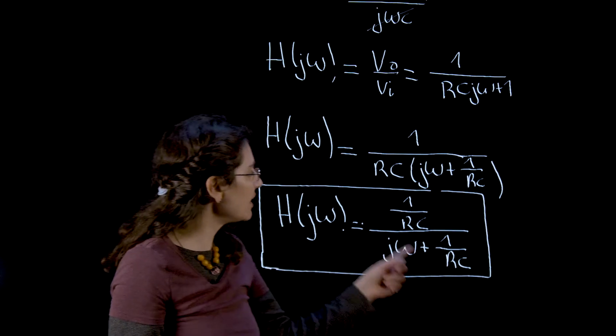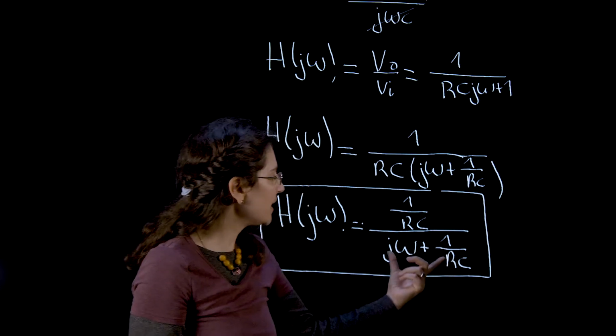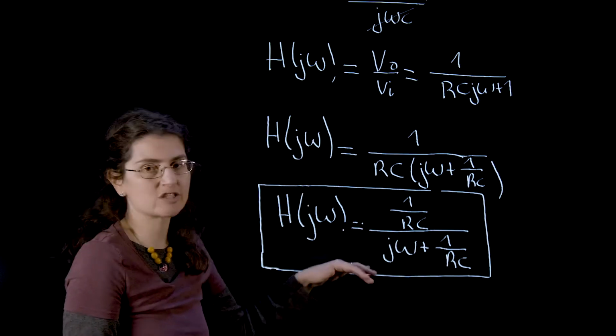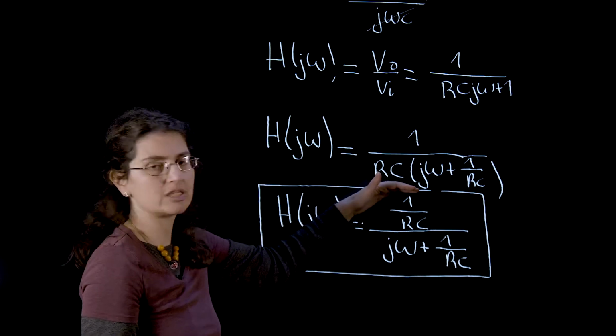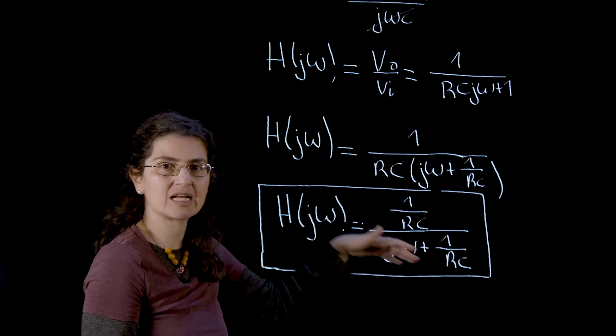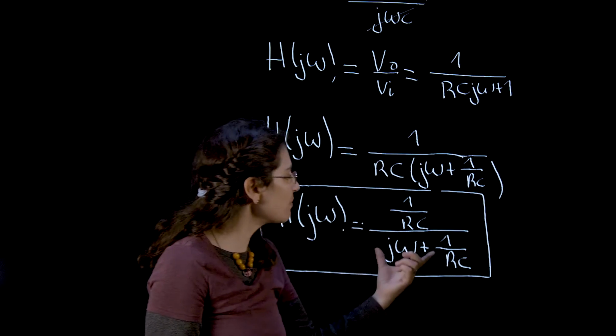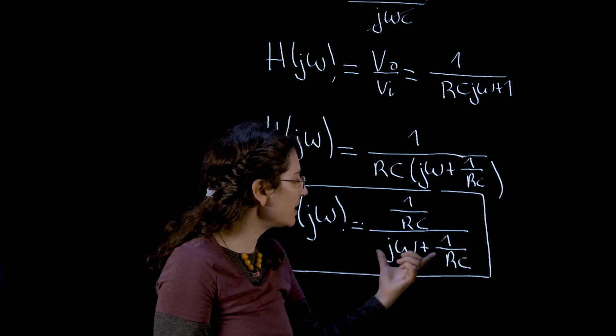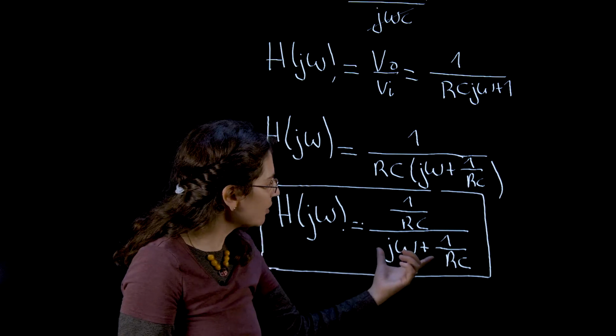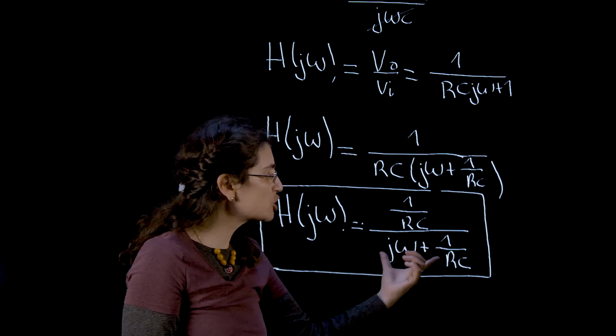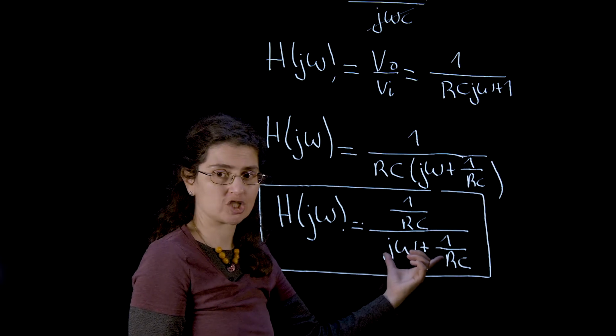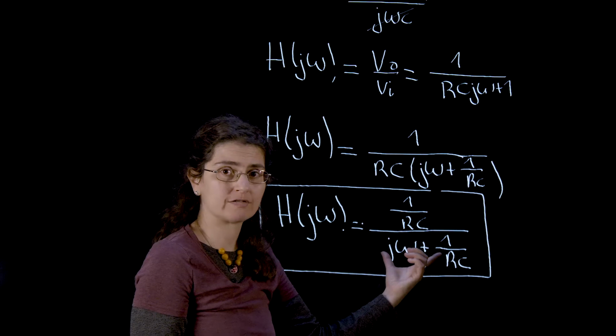And it is a very important point here, because what we always have in transfer functions is a quotient of something. We have a numerator and a denominator. And in the denominator, it's a very important thing here, because the roots of the denominator of the transfer function give me what's called the poles of the system.